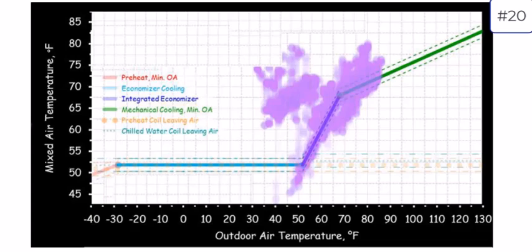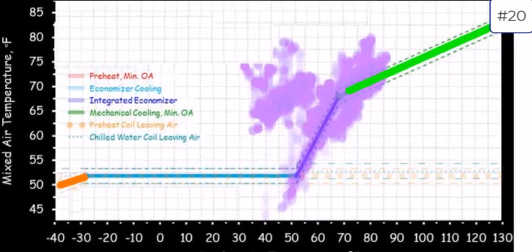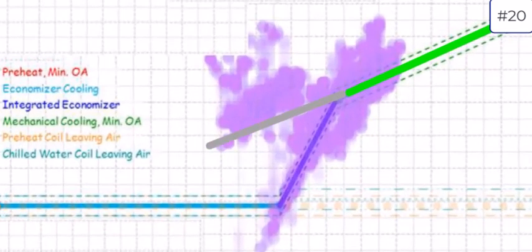Well, the answer we're looking for is that the return air is overused. The way we can think about that is that we would expect to be on minimum air when we're on the green line up here, and we are on the orange line here, where we tend to follow that curve in areas that have outside air conditions where we can economize while we're cooling, or economize and modulate the dampers to meet the mixed air temperature set point, somewhere around 52 degrees.